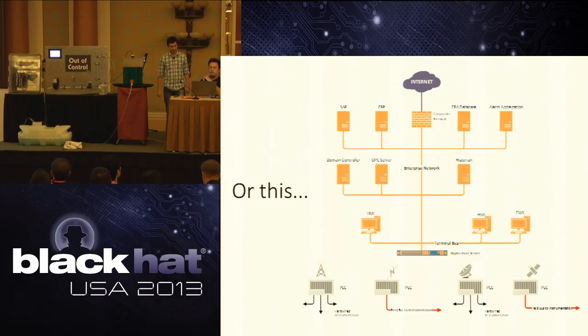And even worse is no routers at all, or no firewalls, where everything is on a flat network and everything can talk to anything else on the network. Yeah, anything from your SAP up to your web server can talk directly and is on the same LAN, broadcasting, on the same LAN as your actual PLCs and your controller hardware.